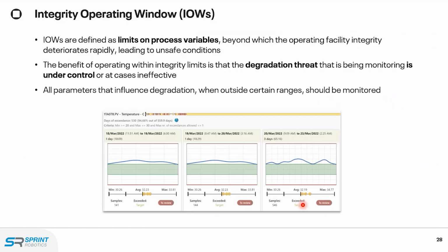We're going to flag and record those exceedances and give them back to the corrosion engineer and the process engineer, who ask what you want to do with that. Review that exceedance. If the exceedance was a one-off, you just ignore it. If there was a process change, you have to go back to your RBI and your corrosion calculations. Likely, if your temperature went up, your corrosion rate will change. That will trigger some additional verifications that, at the end of the day, have to be done by people. They still have to go back and review that outcome.